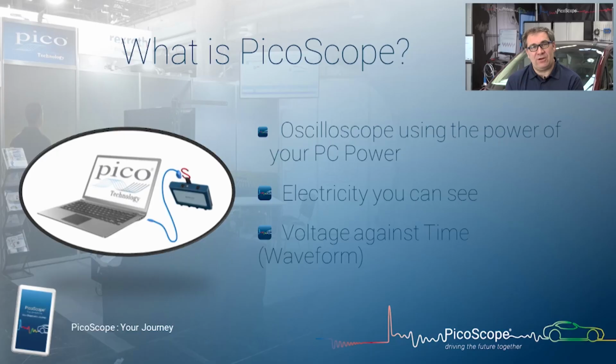Very simply, it's a diagnostic oscilloscope that we connect to our laptop, and we use the power of that PC to drive the software, which in turn gives us everything that we need to look at and analyze the waveforms. Our waveform is simply voltage against time.